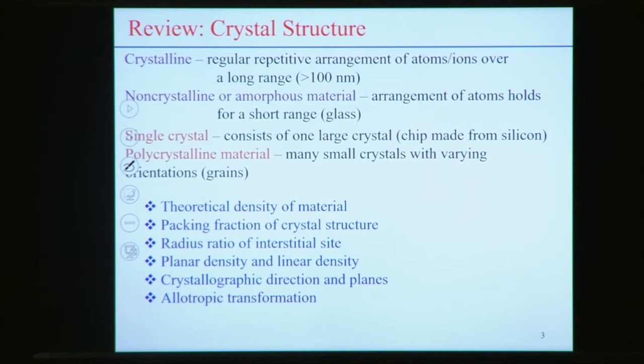So that allotropic transformation is sometimes helpful to find out the change of the volume fraction within the unit cell when there is an allotropic transformation, and how it actually influences the structural form. This is helpful to understand the plastic deformation behavior when you analyze the change of the volume, which induces some amount of strain, and this is very much confined to the microstructure